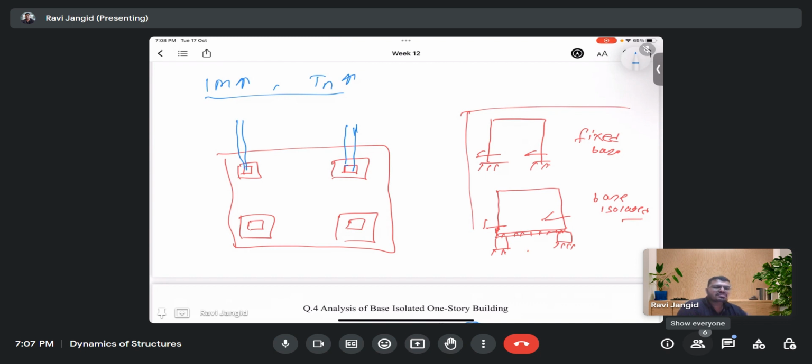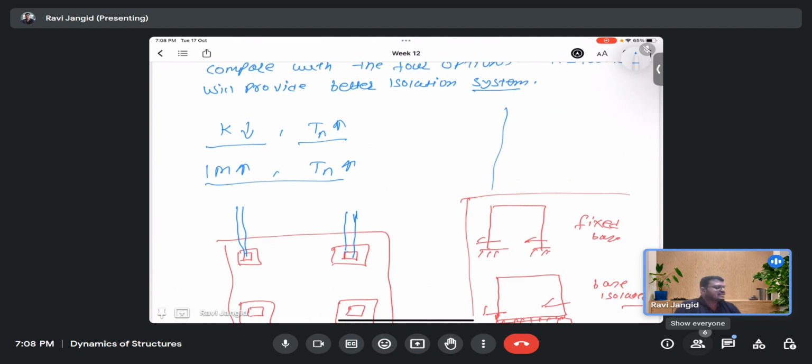Okay. But in the class, sir has shown one video, like in a ground floor. I am thinking you are talking about that. There are some pedestal kind of things coming from the parking lot, and there you have the isolator, and then your beams and columns are resting on that. That is the image from the Bhuj earthquake, I think. After the Bhuj earthquake, they isolated the hospital in Bhuj, Gujarat. They took the pedestal about 1 or 2 meters in height, put the isolators on it, and started the construction.